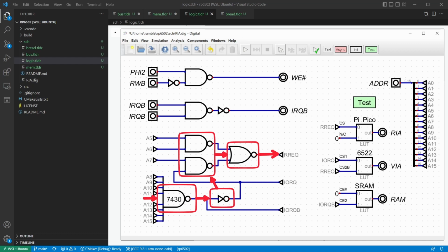There's a couple ways to fix this. Either you figure out how to deal with the speed you have, or you make it faster. Half a clock cycle is unreasonably slow, so let's consider making it faster first. We could speed things up with programmable logic. Everything I know about requires programming hardware, and we don't want that. It also seems a bit extreme. Going at this head-on would simply be buying faster chips. Another way of saying this is we need to switch to a different logic family.